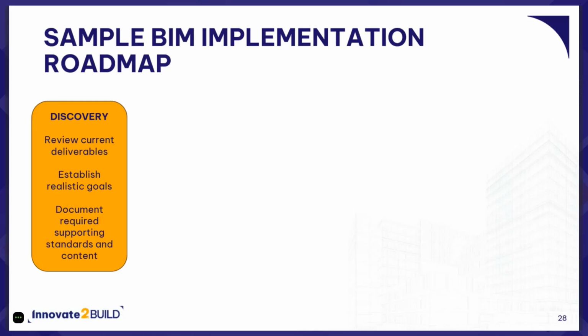All of that mundane stuff, as well as things that you may not normally think about if you're coming from, say, an AutoCAD environment and moving to Revit. Things like view settings and view templates and pre-configured views, lots of stuff around views when you implement Revit. All of that stuff should be documented somewhere. We'll talk more about that in a minute. That's extremely important, and that's where a lot of people miss the boat. They just go ahead and they develop their project template, which is where most of those standards are stored, and it's a critical part of any implementation, but they don't document it, and that can cause problems down the road.